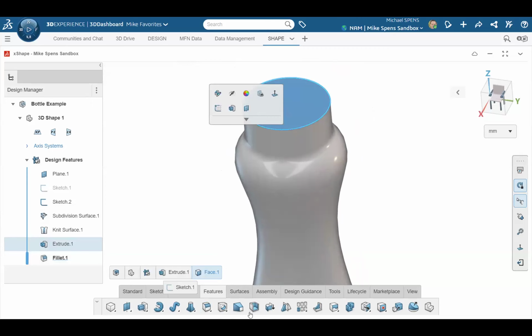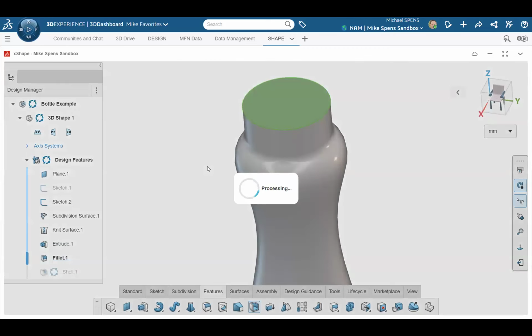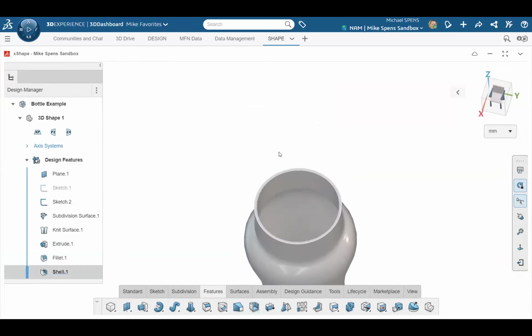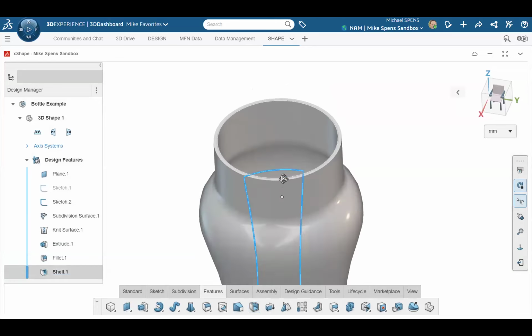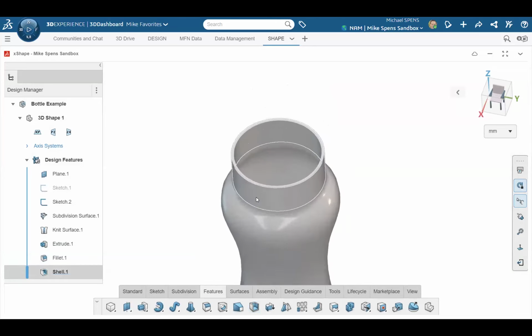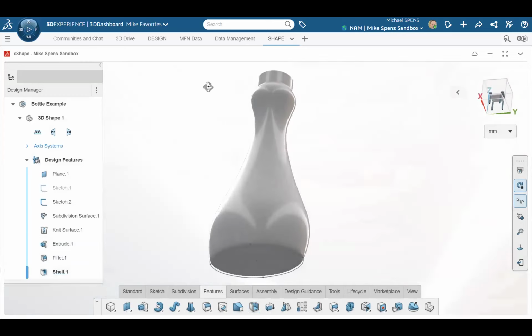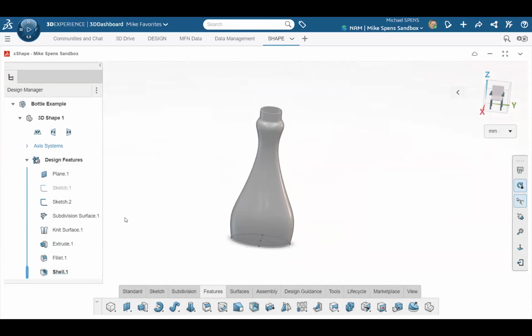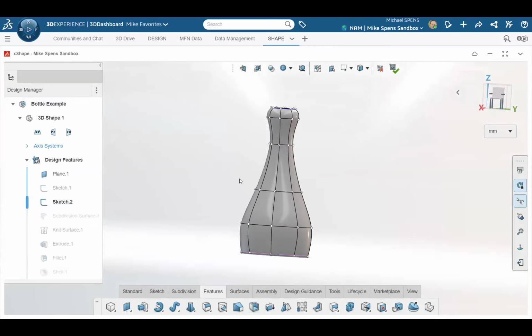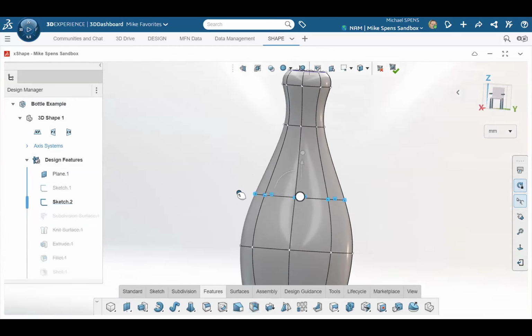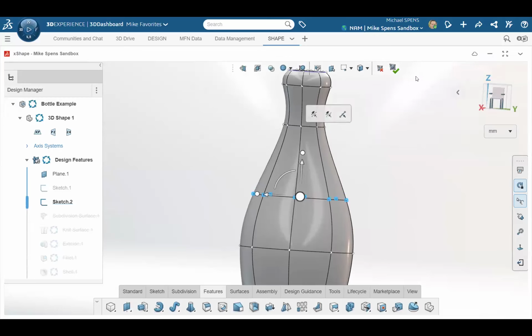Okay, cool. So the workflow gets a little more complicated because all of a sudden you're starting to use a couple different utilities to finish your geometry creation, right? But I extruded this neck on, put a regular old fillet, shelled it out just to illustrate, yes, you do still have all those capabilities. But now I've got the power of being able to say, let's maybe make this ugly, but let's bulge it out here a little more.